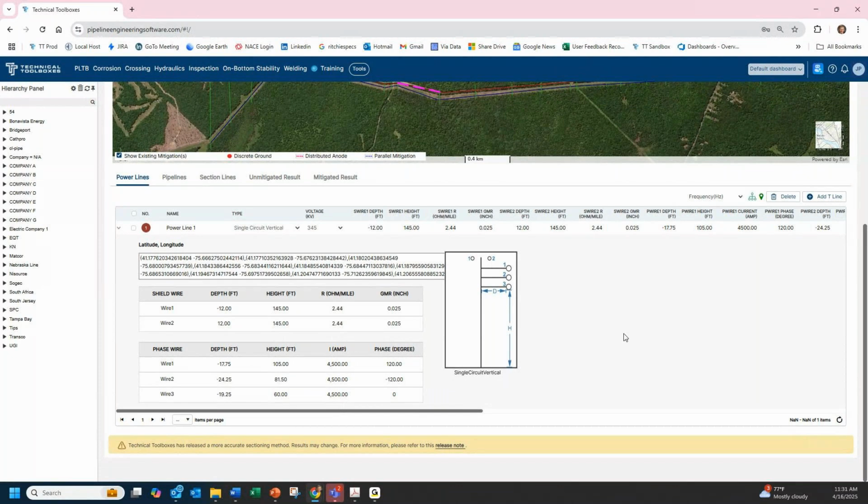But generally, for induced AC issues, they counteract each other. What we're dealing with is the phase right here. So we have to keep in mind that generally it's the closest phases to ground that we're concerned with, but they all have an impact, and they're separated, and that makes it a lot different than when you have something underground.